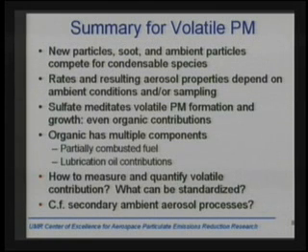So I'll leave you with that, and I think I've summarized my conclusions already, but maybe just to go through them quickly. There are three different contributors here: new particles, soot, and ambient particles. All compete for the condensable species. The rates depend on ambient conditions and possibly sampling. The sulfate mediates volatile PM formation, even as organic contributes to it, and the organic has multiple contributors, partially combusted fuel as well as lubrication oil. How we measure this, particularly for engine certification, and what could be standardized is really an open question because so much is going on. And we also then have to compare to secondary atmospheric ambient processing, where SO2 and the NOx end up contributing to volatile particles, and whether those are perhaps even more important than what we're studying in this context.